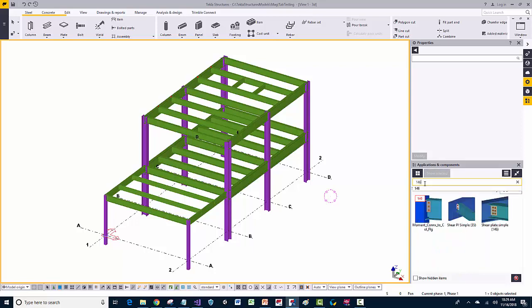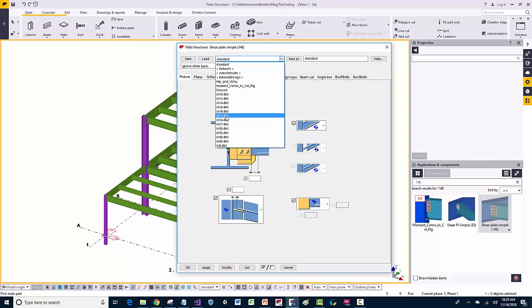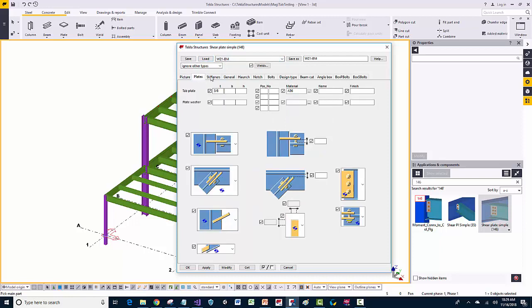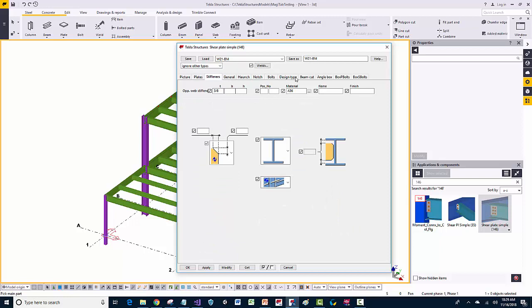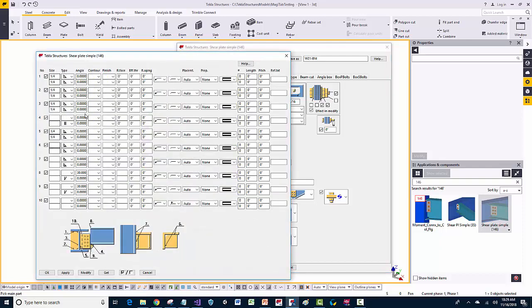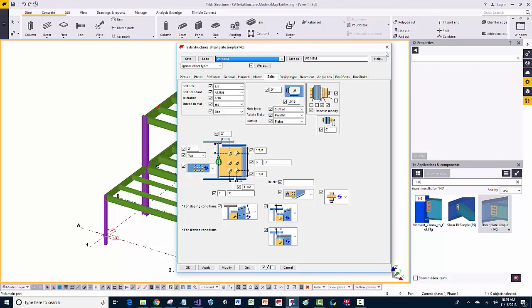After we reopen the model, type in a connection number here, open up its properties, we'll now see a specific attribute file with all of the settings and everything created, including the setback, the plate sizes and material grades, all of the bolt edge distances and the connection edge distances, as well as the weld size information, all filled out here automatically for you from the Excel spreadsheet.